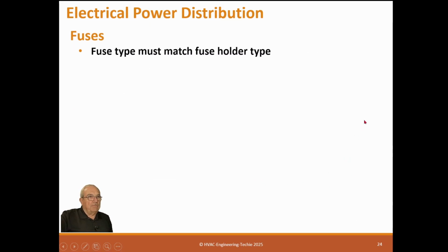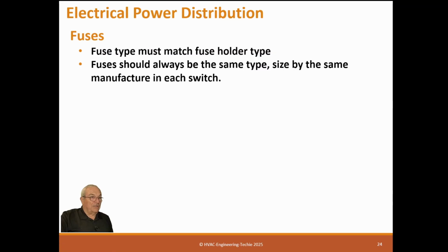Fuse type must match the fuse holder type, obviously. You can't put a bolted one in a ferrule holder. It's not going to work. Fuses should always be the same type, same size, by the same manufacturer in each switch.